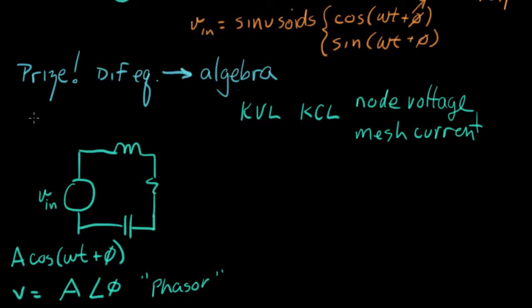So the other thing we're going to learn about is how to transform a circuit, so we can use this sinusoidal steady state analysis. So the inductor, it gets transformed from L. Instead, we write down SL, where S is that same natural frequency. Whenever we have a resistor, we write down just an R, just like we usually do. And whenever we have a capacitor, we write 1 over SC. And again, this S is the same thing as we had before, the natural frequency. And in a future video, we'll justify why we can make this transformation and what this means.